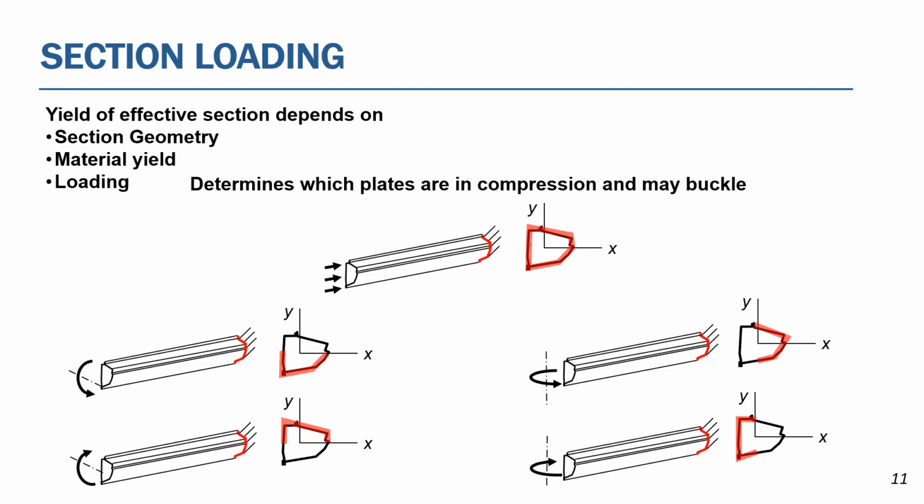Very good, thank you. There's another one which is, I think, very interesting. Does the spot weld location on the flange affect the buckling condition? Where the spot weld is positioned on the flange, would it affect the buckling condition? Yes, most definitely it does. And GAS realizes that, and it predicts the proper results.